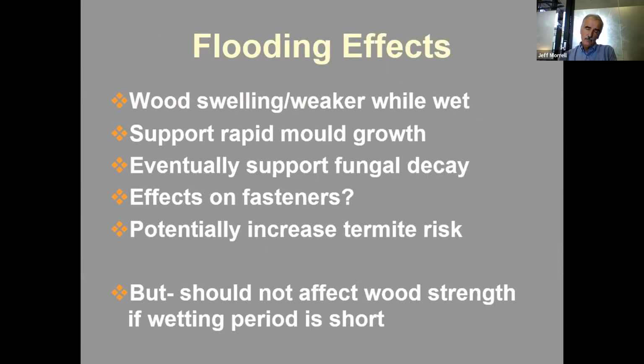The fasteners may need to be looked at. The biggest issue you run into with flooding is that it's going to support rapid mold growth. So the fungi will grow very quickly, particularly on gypsum board, because it's got all that paper to grow on. Eventually, if you let it sit long enough, it'll support fungal decay. If you let it sit long enough, it'll damage the fasteners. It may increase the termite risk, and we are seeing more termite attack in Brisbane since we had the flood. But it doesn't really affect the wood strength once the wood is dry. So you have to remember that it's repairable.